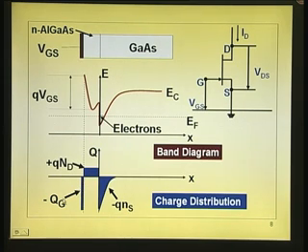Now, at this point, if I increase negative charge here, what happens is, as we have just now discussed, this potential barrier reduces. If this potential barrier reduces, surface potential here reduces, what happens to the charge here? It becomes less n type, less band bending. It is like an inversion layer. The band bending is more, electrons in the inversion layer are more. The band bending is less, electrons are fewer. So, by increasing this voltage more negatively, you actually have a reduction in the surface potential, reduction in the potential change here, which reduces these electrons here. Okay. And depletion layer also collapses because potential is reduced.